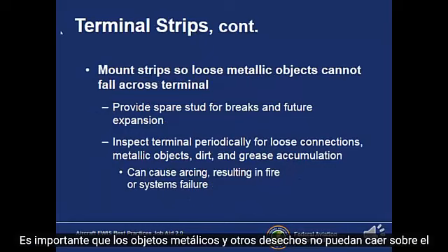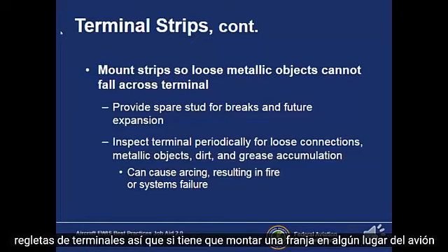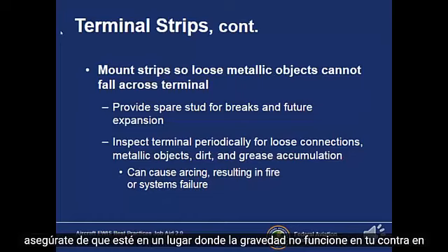It's important that metallic objects and other debris cannot fall on top of the terminal strips. So if you do have to mount a strip somewhere on the aircraft, make sure that it's in a place where gravity is not working against you.